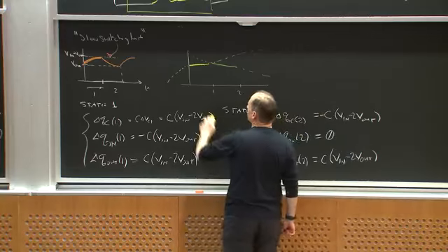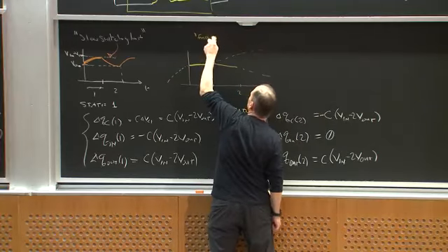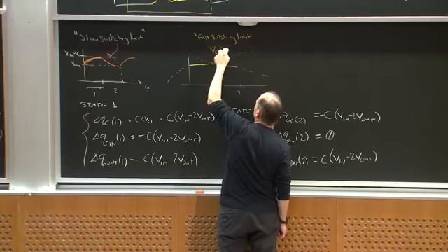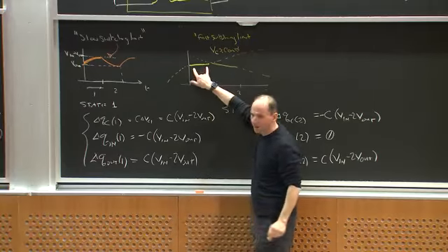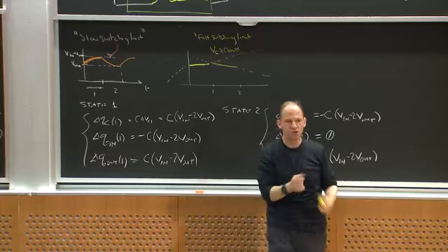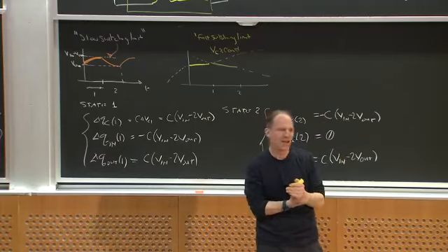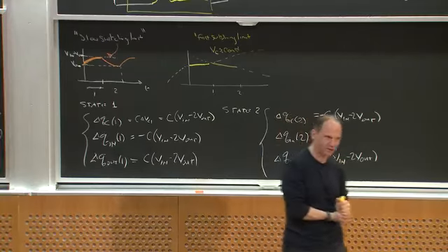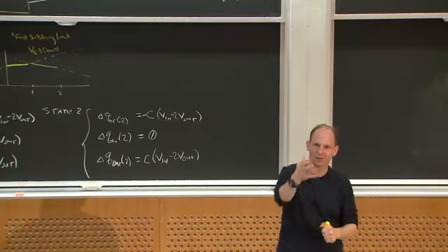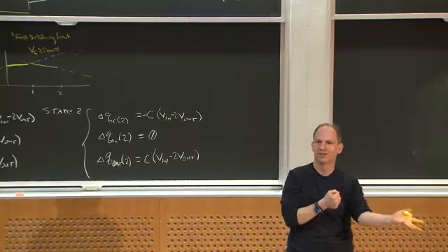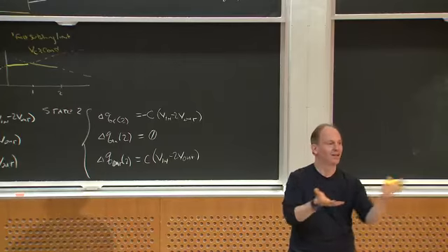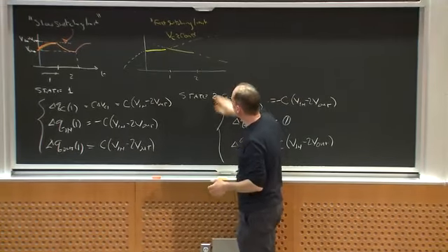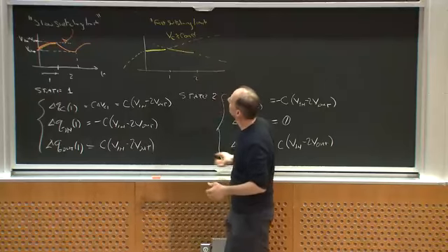So I can almost think, in the fast switching limit, VC is almost constant, right? I don't have enough time to charge up or down substantially. The delta voltage I get is nowhere near the full swing, okay? And I can just start to think about the capacitor as being a constant voltage. But it's a special constant voltage because, nonetheless, if I'm going to be in periodic steady state, however much it charges in the first state must balance the amount it discharges in the second state, right? I haven't gotten around that kind of rule. But nonetheless, we can think about this fast switching limit as the capacitor voltage almost becoming constant.